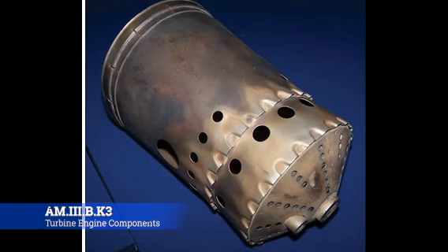So it's oriented correctly to those holes and liners and louvers and all that good stuff. Now the louvers are also provided along the axial length of the liners to direct a cooling layer of air along the side of the wall. Because remember, it's not just about making the combustion, but also cooling that hot air down low enough to where it can actually be used. Now, this layer of air tends to control the flame pattern by keeping it centered in the liner and thereby preventing the burning of the liner walls.